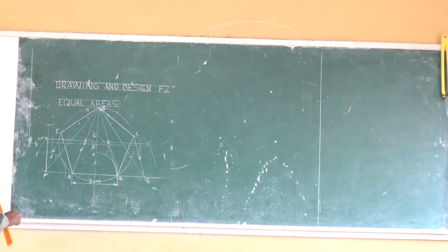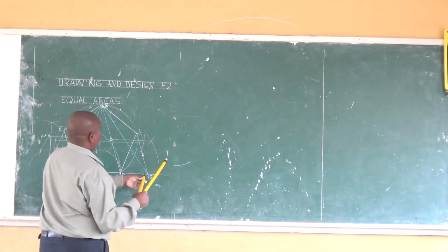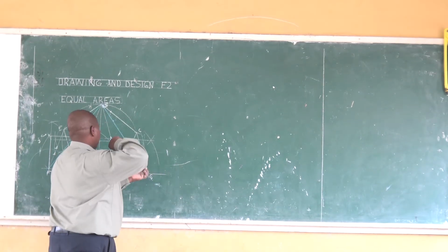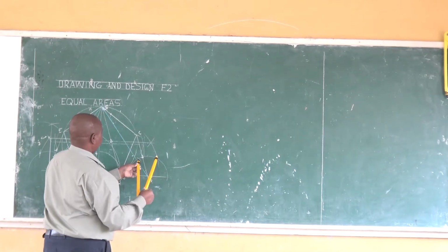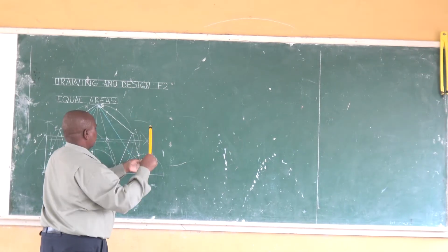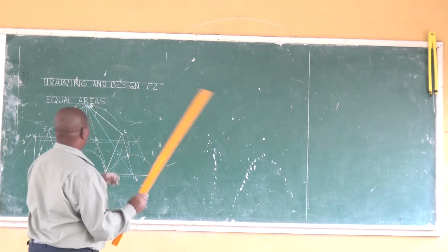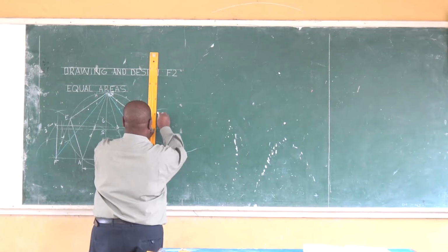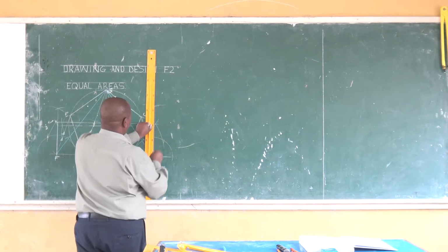This one, you can proceed to outline because it's a final point. Similarly, erect a perpendicular from point G. Once again, draw an arc and proceed to have 3 steps, then bisect that resultant angle and join it with this point G so that you have that perpendicular line.